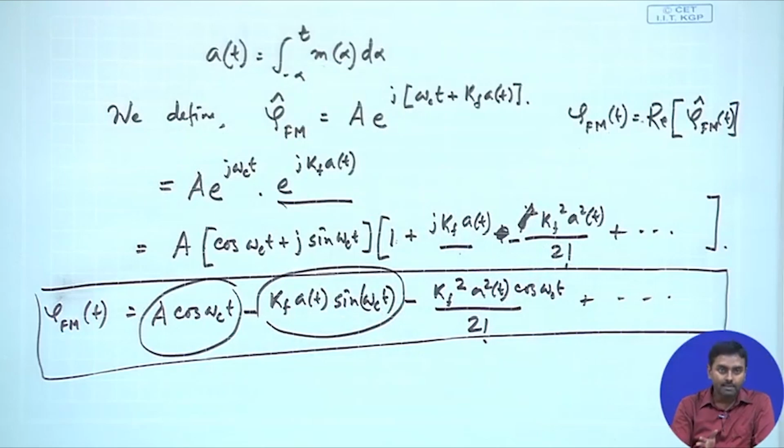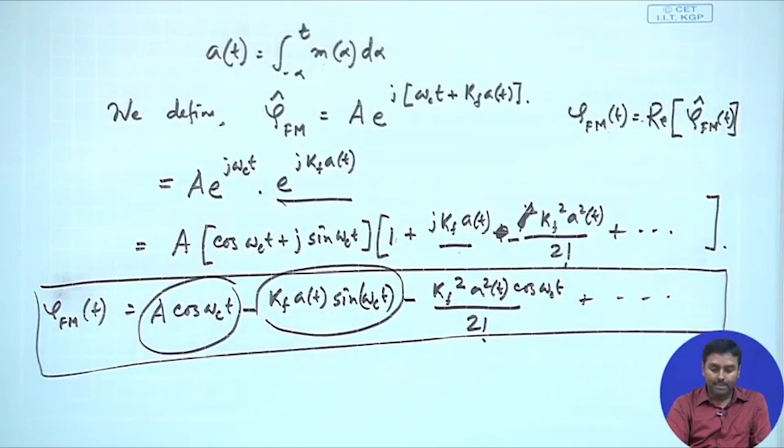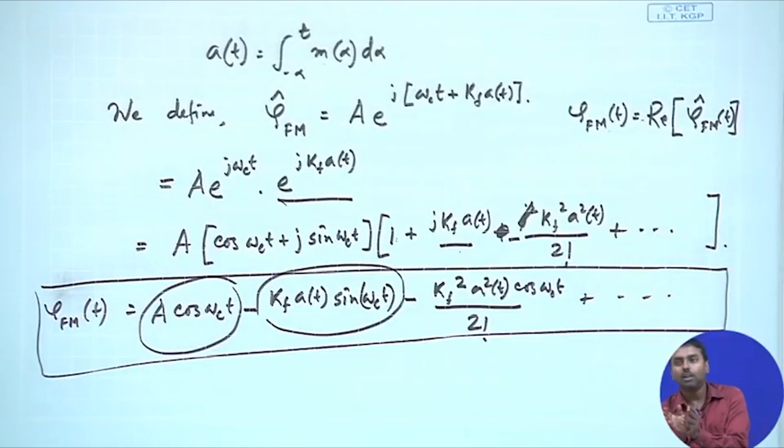That is something we can represent. If I put that, immediately I calculate the band will remain the same. So, A(t) in the frequency domain has equivalent band as m(t) or M(f). If I do this modulation, the first two terms I inspect, I have a carrier and an almost similar DSB-SC modulation which takes the entire band. So, initially whatever we have said, that FM probably might have 0 band, that is not true. From this analysis we can already see.